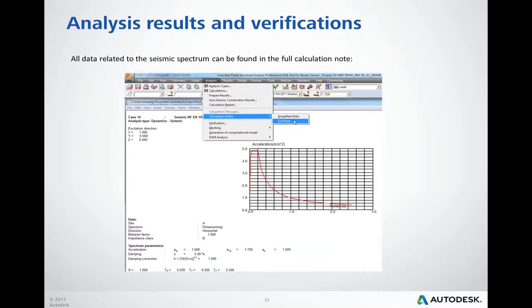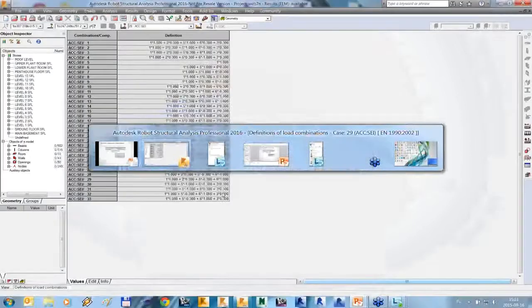All data related to the seismic spectrum can be found in the full calculation node. Calculation node can be opened from the Analysis menu, then the Calculation Node sub-menu. Let's look at our model.